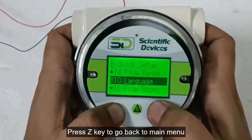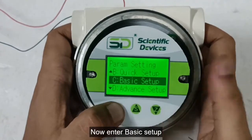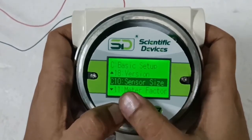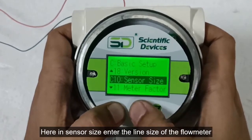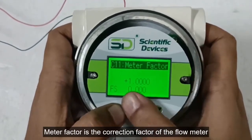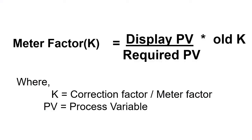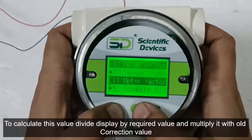Press Z key to go back to main menu. Now enter basic setup. Here in sensor size, enter the line size of the flow meter. Meter factor is the correction factor of the flow meter. To calculate this value, divide display by required value and multiply it with old correction value.